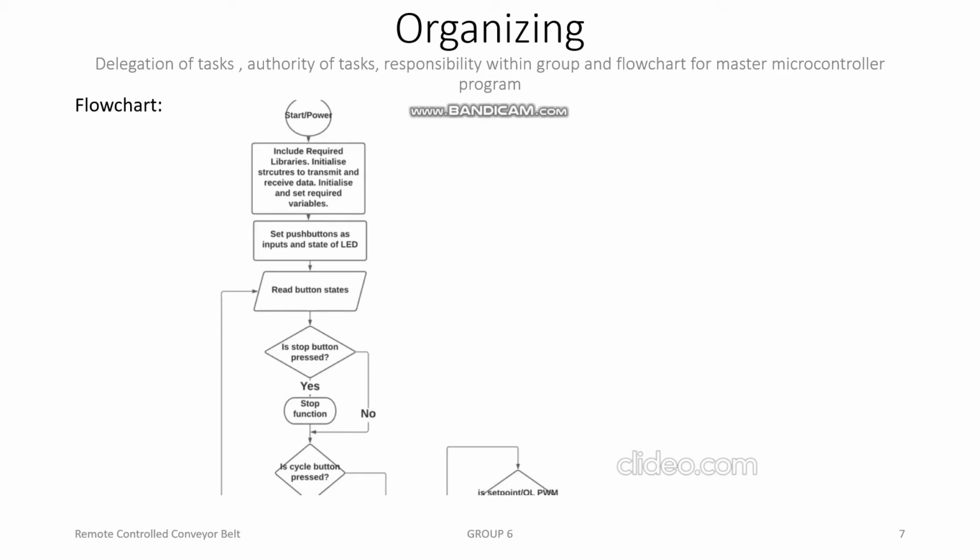Once the relevant components were chosen, Arduino ports were assigned to the chosen components and a circuit schematic was drawn up. The program for the user interface was then coded on Arduino IDE in accordance with the flowchart. The program was then uploaded to an Arduino and the device was constructed within a plastic housing while making reference to the circuit schematic.